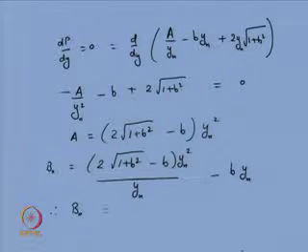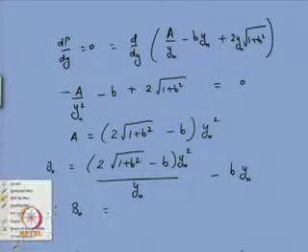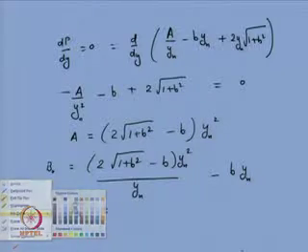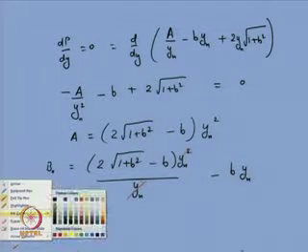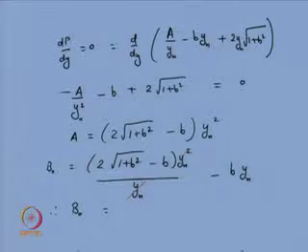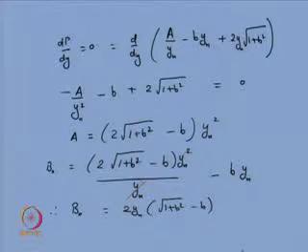Therefore, rearrange the terms and cancel off the terms whichever is obvious to you. This thing and this thing can be cancelled off. Like that, you will see that you are going to get B0 is equal to 2y_n into root of 1 plus b squared minus b. Or you can also see that for the hydraulically efficient channel cross section, the normal depth should be equal